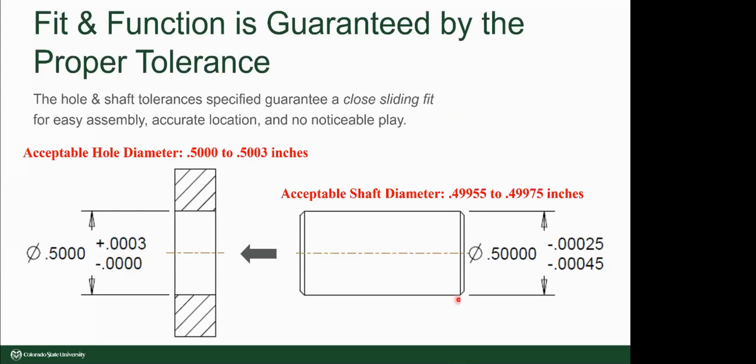So let's come up with a purpose. Let's say that the purpose of this shaft is to precisely locate a third mating part that's not shown here. The third mating part will slide onto the opposite end of the shaft on this right-hand side, and it needs to be properly aligned with another feature on the part with this hole, some other feature that we can't see right now.